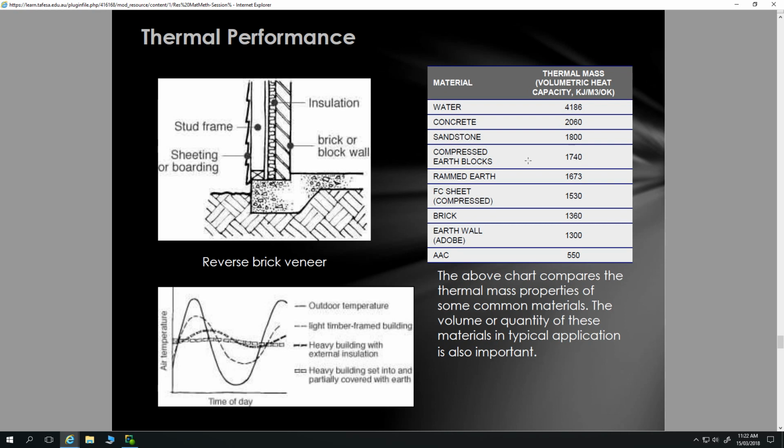I'm not exactly sure what you put into a compressed earth block. I don't think you'd want to put any straw in there. I think it works very much the same as rammed earth, but I have no experience in it. Basically, you've got a rigid steel small formwork that you place earth into, and then this long arm that you pull down, and that compresses the earth and makes a block. So it makes a masonry block with little addition of cement, just using dirt for it. So that's compressed earth blocks.